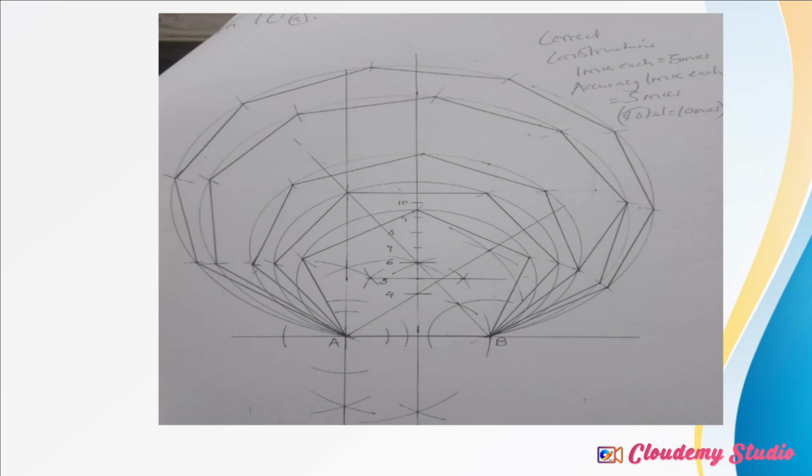Mark your first starting point as point A. Then using a ruler and a pair of compasses, measure the length, which is 50 millimeters. Standing at point A, mark your second point, which is point B. So if you look keenly at point B, there is an arc to show that I did construct that measurement. I did not just measure, because I gave the bounding limits of the question that I was asked.